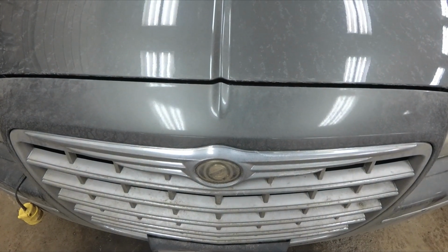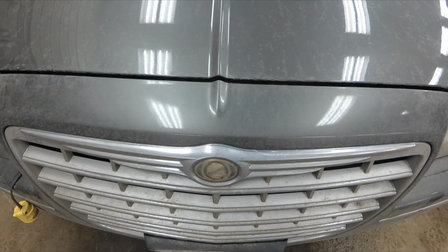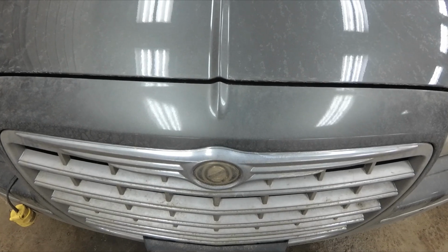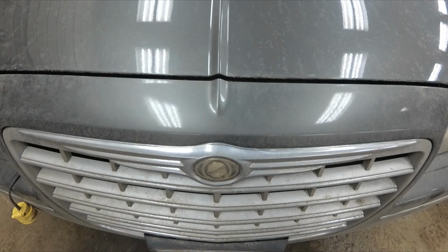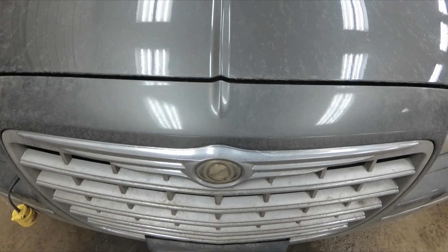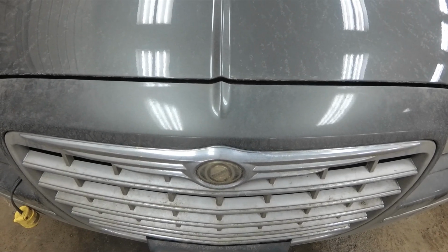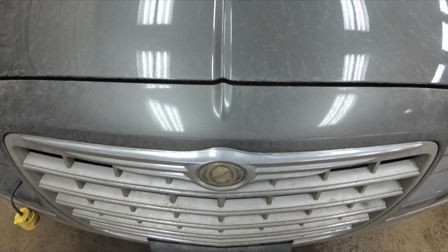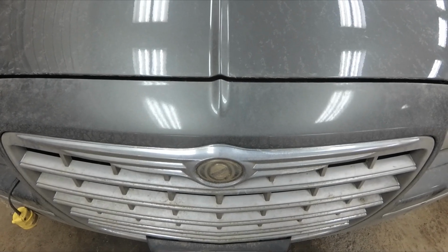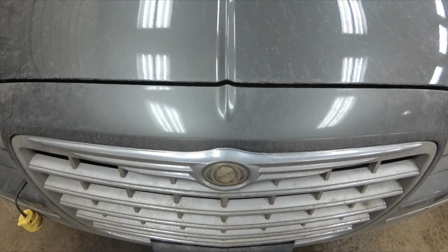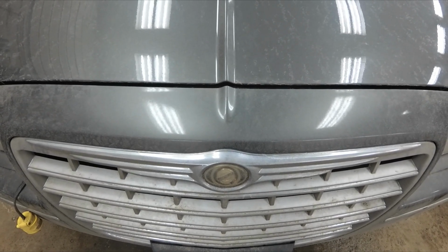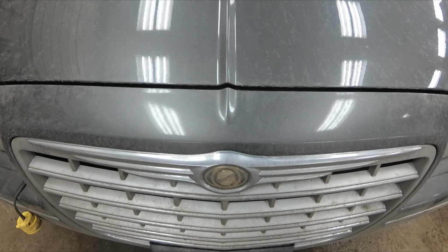Okay, so this morning we have a 2010 Chrysler 300. It was here a couple of months ago and we did some repairs on the ABS system, traction control system, by replacing a speed sensor on the left rear and the speed sensor and reluctor on the right rear. So apparently the ABS light is back on, traction control light is back on. So we're going to connect the scanner and have a look at what's causing the problem today.